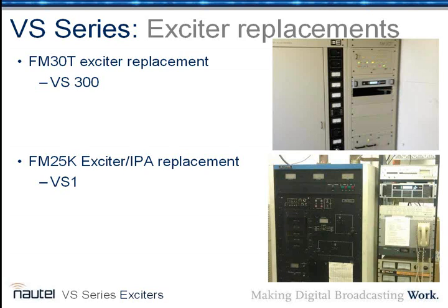And you were also mentioning some changes in audio quality on it. Audio quality went through the roof when we got rid of the FX30. Obviously, a 30-year-old exciter has 30-year-old technology in it. So the sound quality dramatically improved. We no longer needed the composite clipper in front of it. We were running an Omnia processor in front of it, so the sound quality went way up, and the transmitter actually passes the mask. We didn't have to fudge anything anymore. The exciter was keeping it all in check for us.